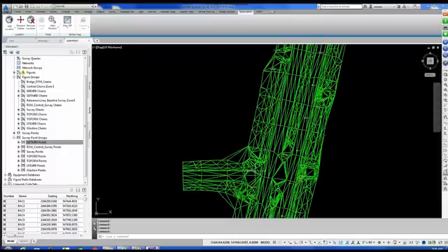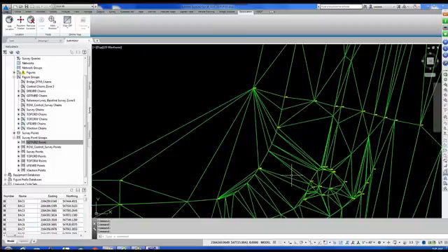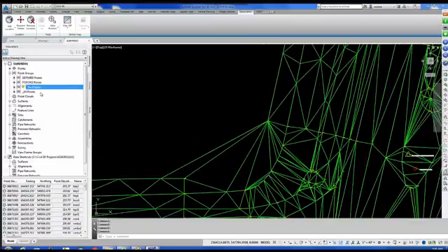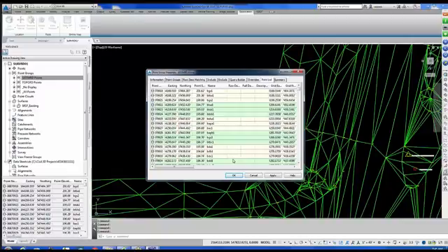All right, so if I zoom in here, you're going to see I have some survey points in here. Now, I need to take those points that I just brought in, and again, No Display needs to be updated. I need to add that point group that I just brought in called GDTMRD points. So if I pick on it and I go to Properties and I list them, you'll see that those are all the points that came in from the survey database, the ones that matched the attribute that I had called ground.